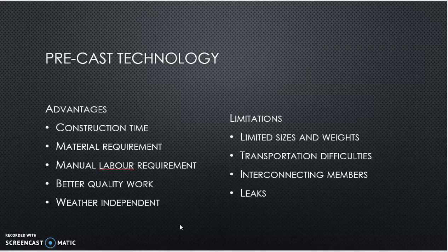Next is manual labor requirement. Since most of the units that are prefabricated or precast are manufactured using machines, the manual labor requirement goes down. Also, as I told you, the supervision is of a better quality, so you get better quality elements used in construction. And again, since you're not storing it at the site, or even if you're casting it at the yard, the period of storage is very less.